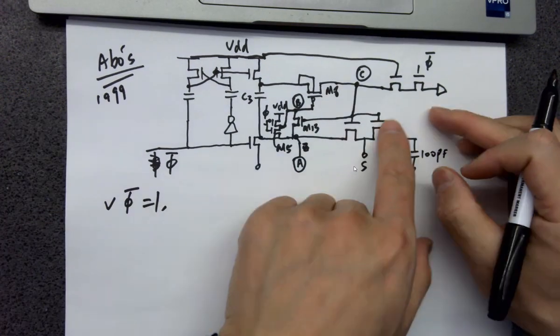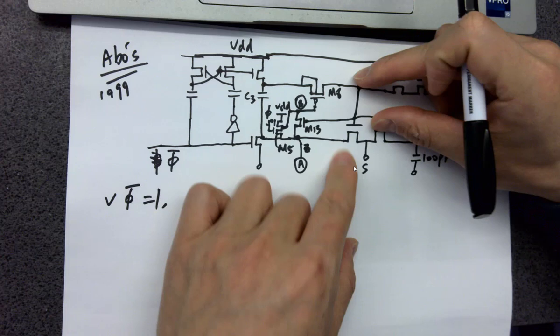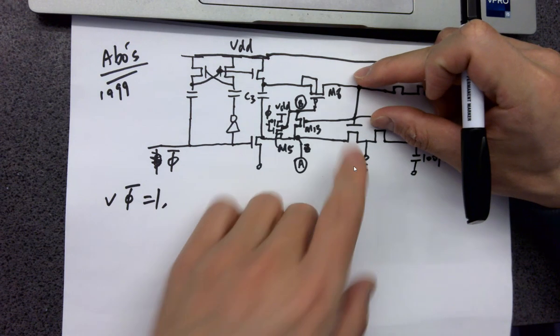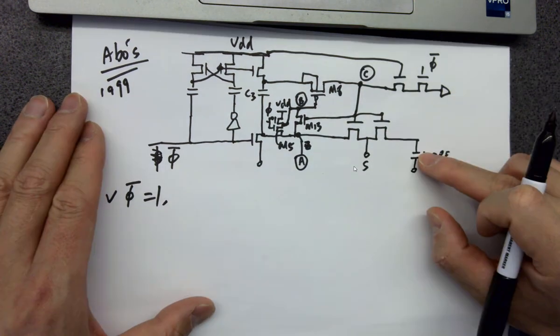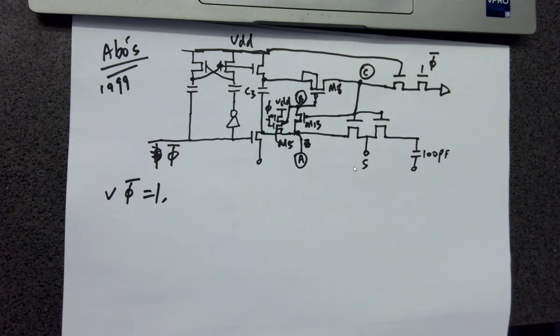Or you can say when it's holding, it's trying to reset whatever charge was previously stored at the gate. So it's holding the voltage over here. You can imagine it's a long flat line in your diagrams. During this period, you have the time to do the ADC conversion. Very important, okay? Also during the same time, the sample and hold is not working anymore. It's just holding. And your ADC, the downstream circuits like the SAR blocks, are working really hard to do all the 9 cycles of conversions.